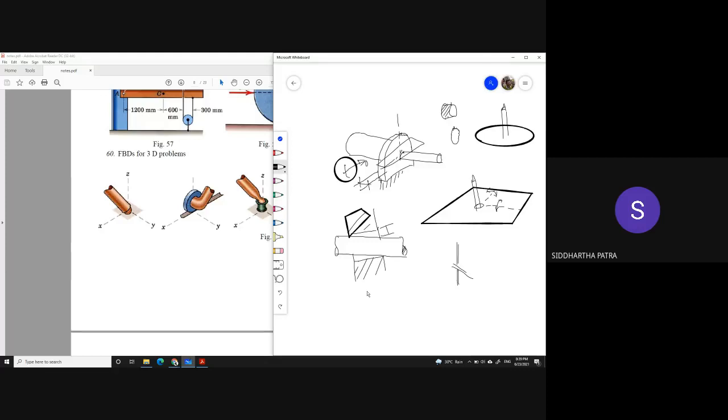I have one objection to that thinking. I don't care whether there is gravity, whether everything is in the vertical plane. If what you are considering the z-axis is the vertical direction, I don't care. The way I propose reaction forces and moments is just by looking at a support standalone. My criteria is what motion it constrains effectively, and then the reaction in the same direction.